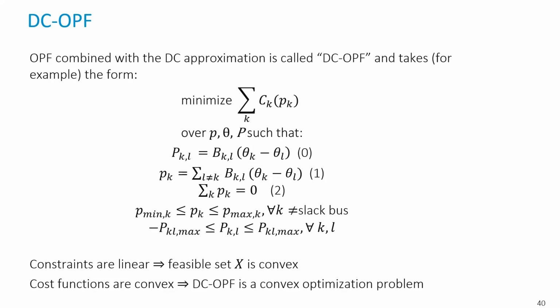At first order, what is the goal of a transmission grid? It is to transmit active power. So where does power flow? Is power flowing now from Germany to Italy, or the other way around? That's the kind of thing you want to know when you control the European grid, for example. You do this with a DC-OPF because that will give you answers to such questions. It will not give you answers to questions such as, how should I control my voltage problems? What should be the set point of my reactive power compensators? Those we will not be able to do with the DC-OPF.